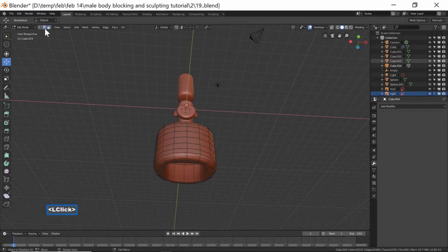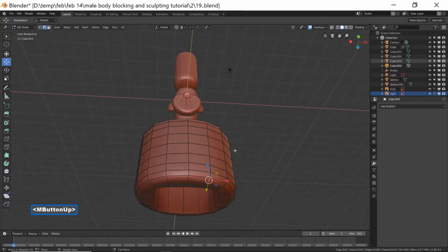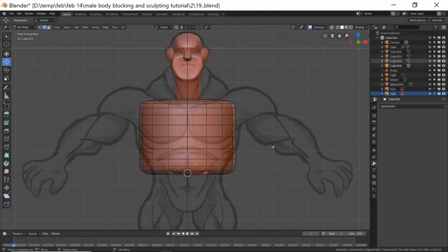I'm going to go to edge select. I'm going to select here. I'm going to hold Control as well as the middle. Well, I'm holding Shift as well. No middle mouse button. Holding Shift and just left clicking. I'm going to press 1 to go back to front view. I'm going to hold Alt, then press O to turn on the connected proportional editing. You click up here. You can do this manually. You can also see that circle there is our connected proportional editing.